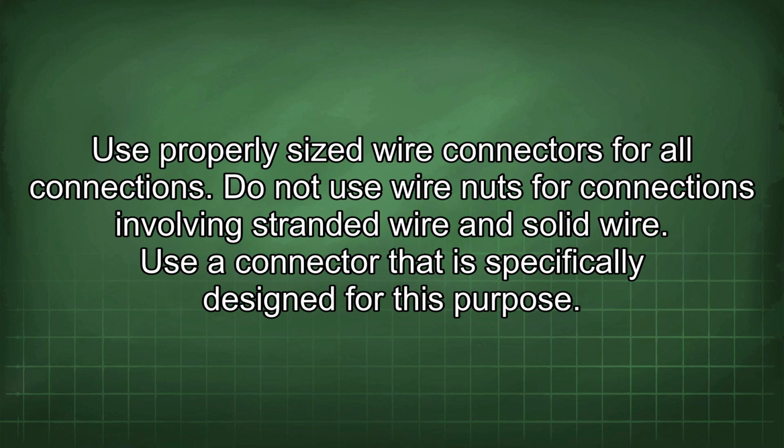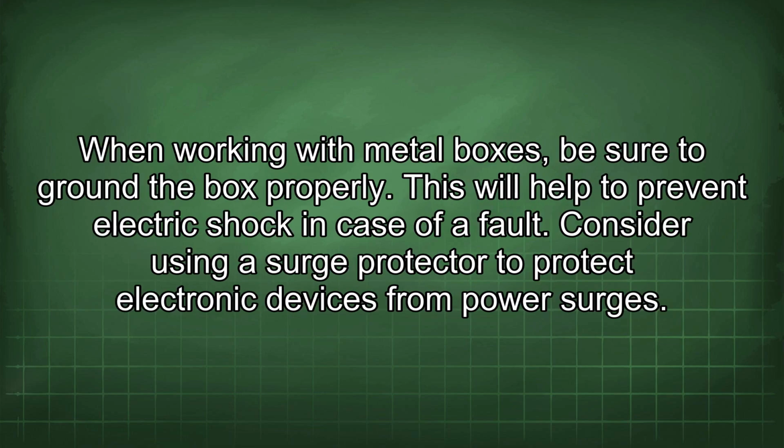Do not use wire nuts for connections involving stranded wire and solid wire. Use a connector that is specifically designed for this purpose. When working with metal boxes, be sure to ground the box properly. This will help to prevent electric shock in case of a fault.